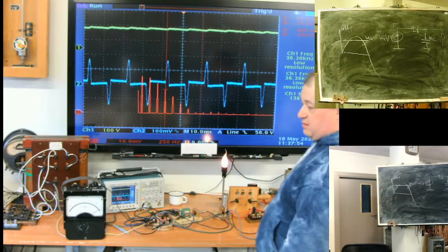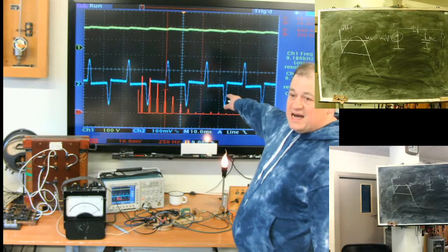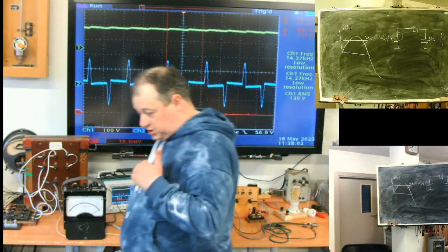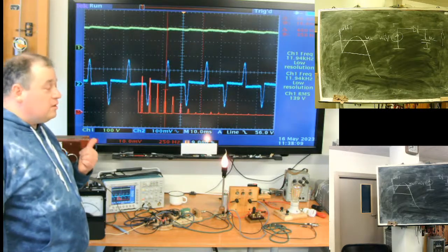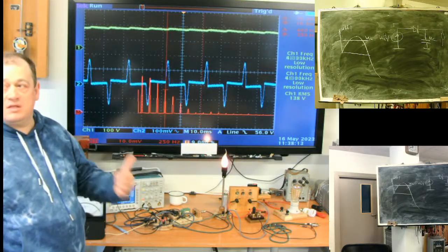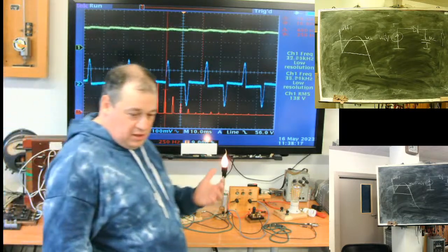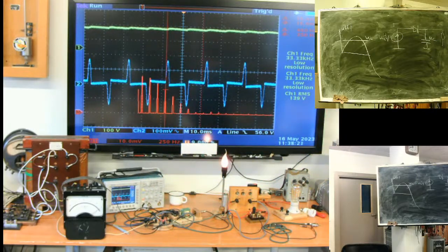When you have a network with high, let's say, output resistance, a low power network, when traditional large generators are connected to the network, the third harmonic circulates in the neutral of transformers.